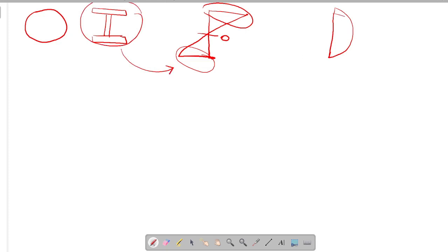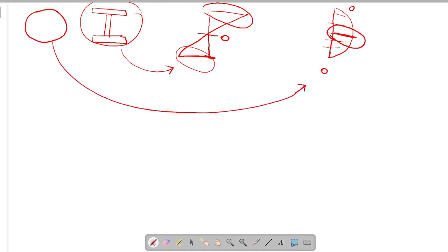If we observe the shear variation, it is maximum at the neutral axis, whereas zero at top and bottom surfaces. That means we need maximum material at the neutral axis. In case of circular section, we know that maximum material is at the neutral axis and the material goes on decreasing from maximum to least at the surface. So in shear, we generally prefer circular section, whereas in bending, we prefer I section. This is a normal trick or easy way to find which section is preferred in case of bending and which in case of shear, if they ask in exams.